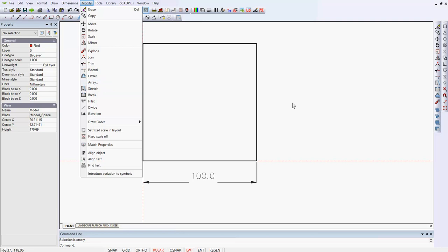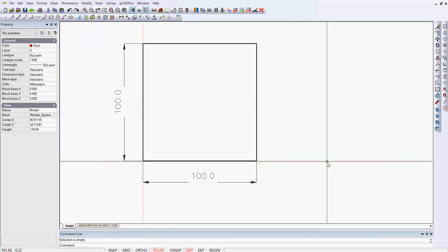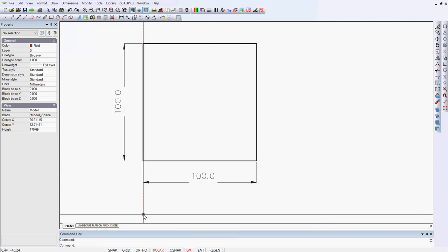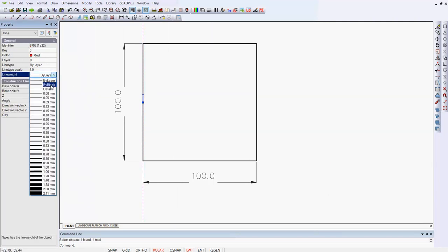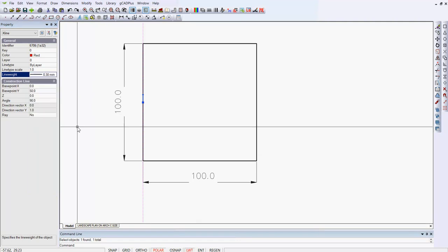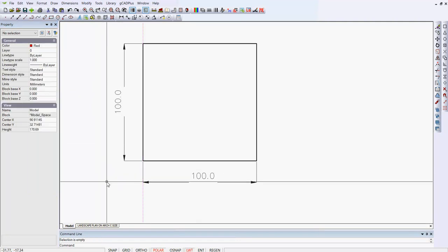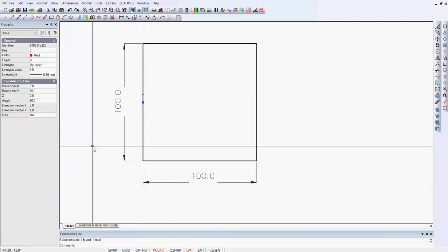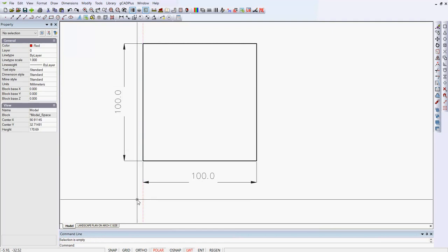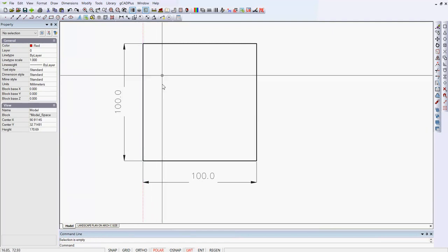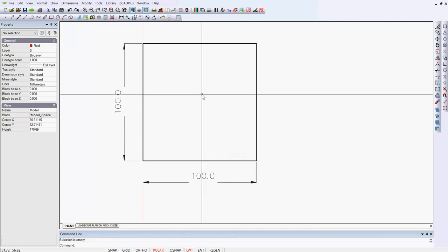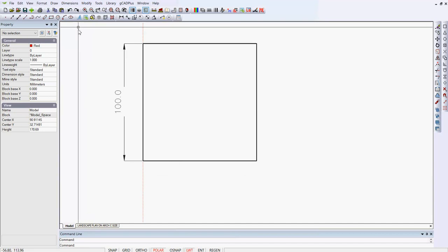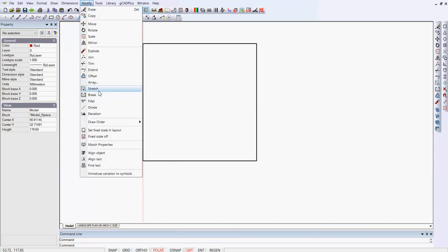Now, just before I do that, this will get a little tricky, because I want to remove this construction line that I put there. I'll leave the construction line running down to the left, although I might thicken it up so we can see it clearly. So, that's interesting, it didn't actually thicken, maybe I didn't set it. I'm digressing, but let me pick that. No, it is. So a construction line, not unreasonably, won't show a thickness, but it's there showing our left hand side. So I can now, and I'll get rid of the dimension.